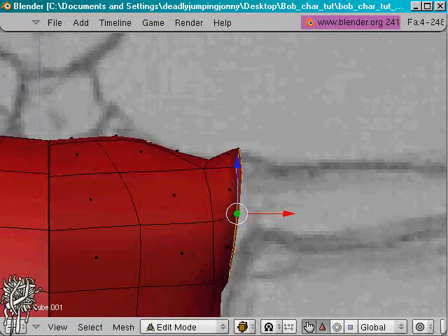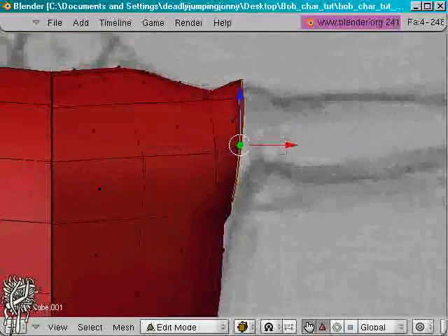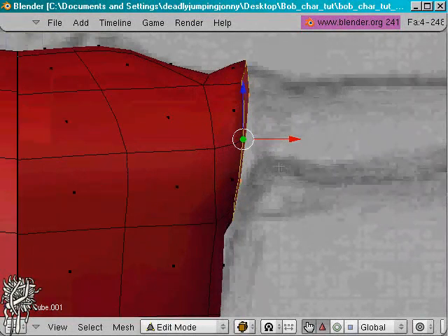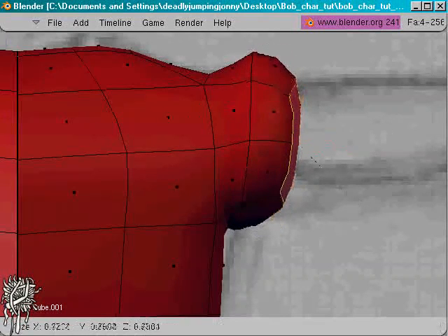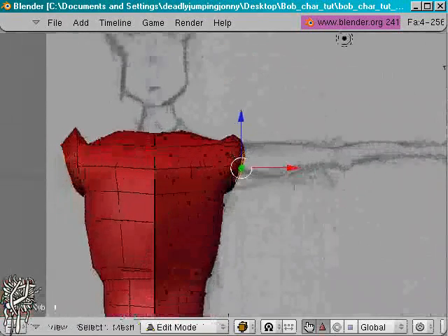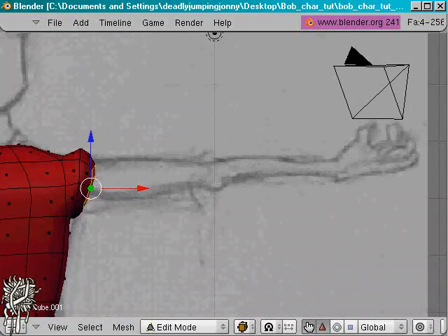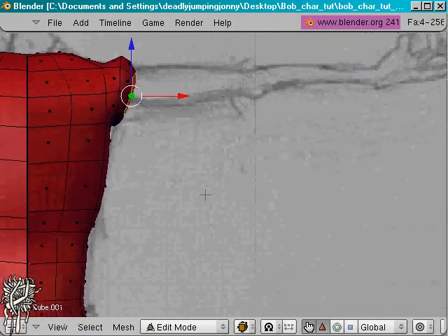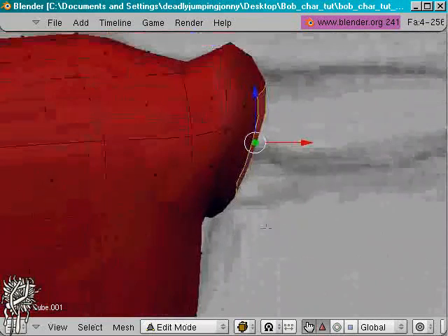We need a kind of sweeping arc round here for the shoulder so it can rotate freely, and well, because this is a very tricky part a lot of the time. Don't worry if you don't get it right first time. It's very hard to create good working shoulders. It can be very frustrating. So extrude again. Scale. Move it along a bit. Rotate. We could do the arm straight out like that, and we also need to think about the position the hand is going to be made in. I did it facing upwards, but since we're not really going to be modelling the hand here, I'm going to just use that as a basic reference to the shape that I'd like, and I'm going to model it directly, diagonally, to avoid causing too many problems.